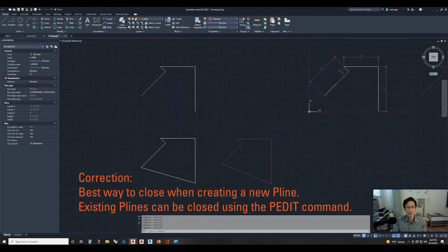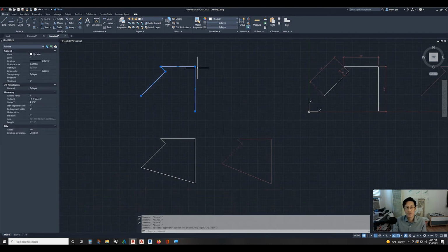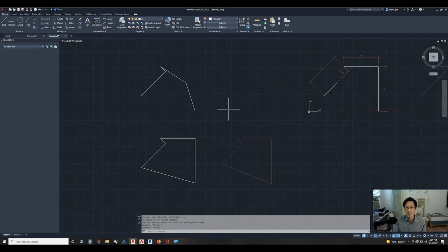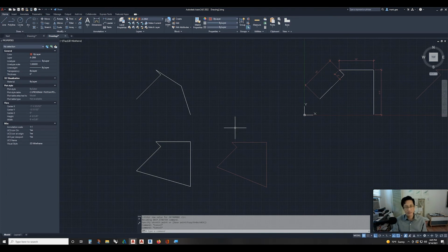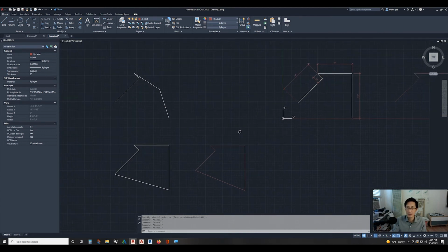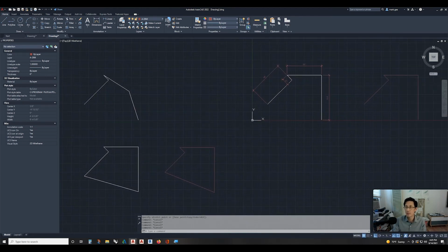And polylines can be edited by moving their grips if you so desire, like such. And we'll get into more of the editing as the class goes on. We can also break apart the polyline into its component pieces or explode it. We can break it anywhere along the polyline that we want. And we'll get into the editing of polylines in a later micro tutorial.